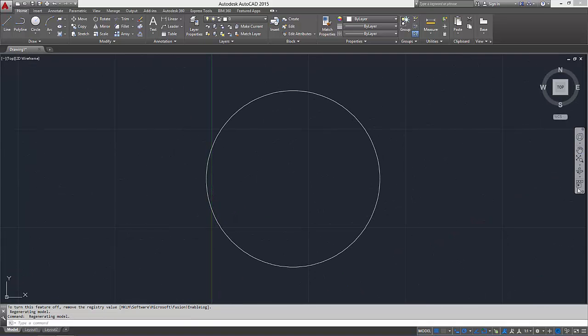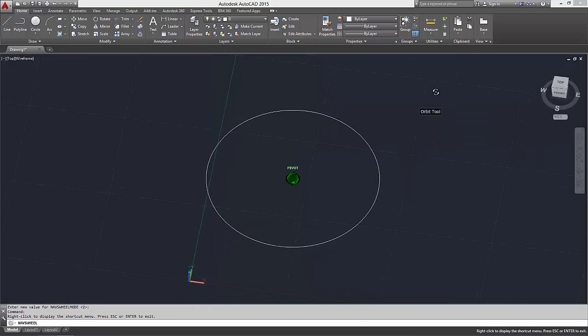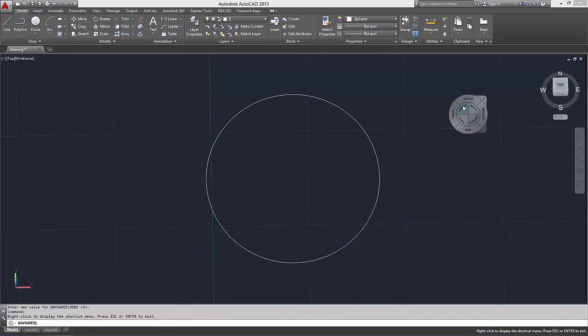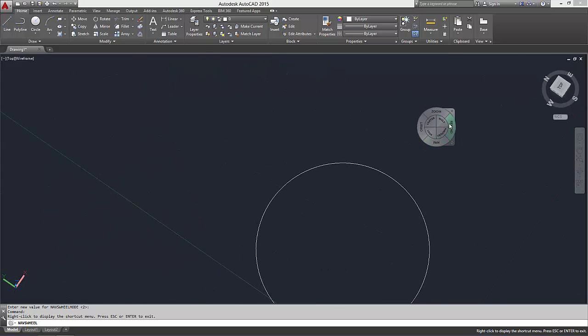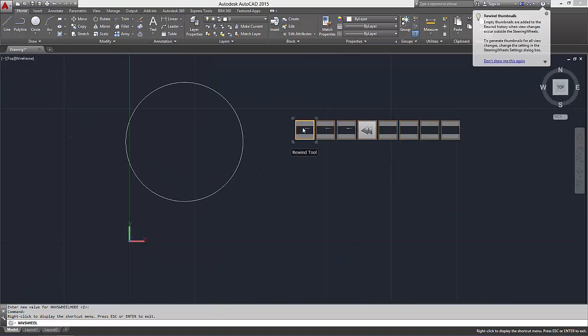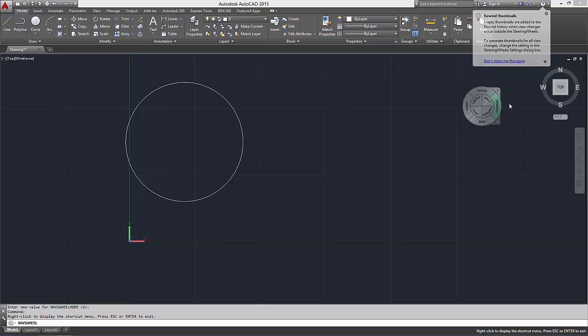This thing here is a navigation wheel, so you've got sort of the view bar along here. So zoom extents, pan, orbit, and this thing here, which is a full navigation wheel. You can drag that out and you can orbit around the pivot point. You can center, so wherever I choose to center my object, anywhere on this line, let go of that, and then I'm going to orbit, and it's going to pivot around that point. I can rewind my views through that, so it's quite useful. That's taking me back to the original top view.